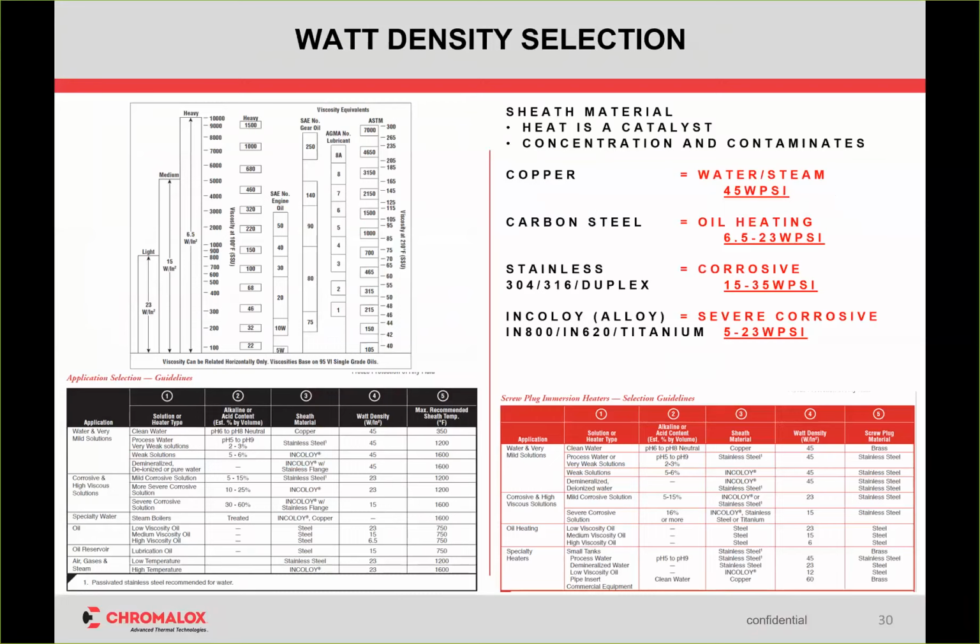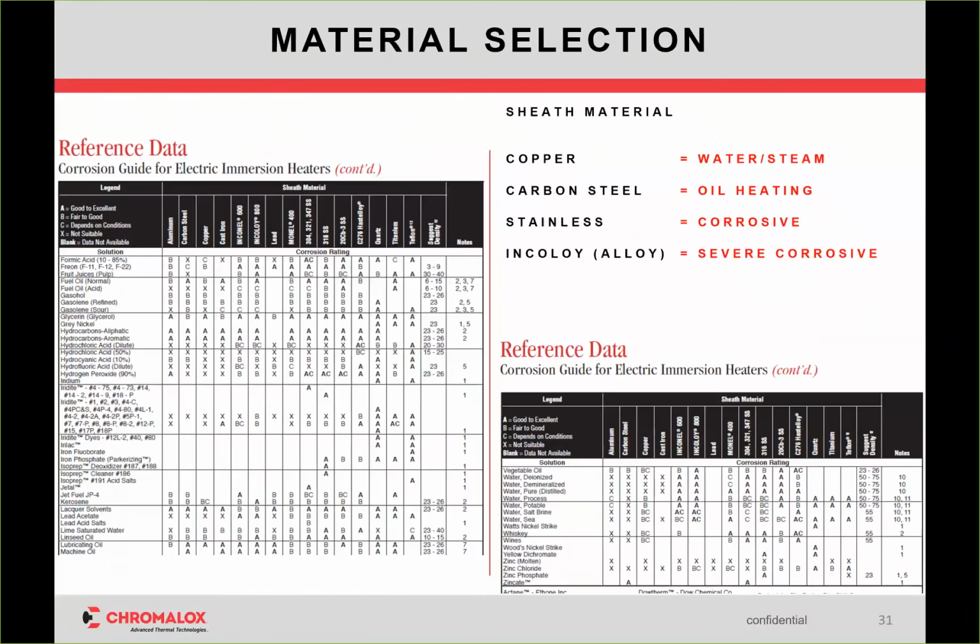We have a couple people who have come recently with a competitor who had distributed watt density. We don't advertise it because we've always had it. We can stretch a coil in a certain part of the element and make the beginning of the element 30 watts a square inch where the ending of the element is 5. We already have that available. And actually, I think they're probably going to put a marketing piece together on that too.